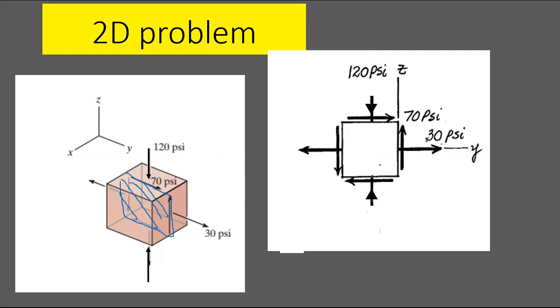So I take that element and you have compression on this face and tension on this face, right? Clockwise shear on this face and anti-clockwise shear on this face. So you know shear is complementary. How to mark on the other face? These two make a couple, you remember. So if this is clockwise, this is also clockwise. If this is anti-clockwise, this is also anti-clockwise. These two make another couple, that is like this couple, the couple made by this, about this, right?